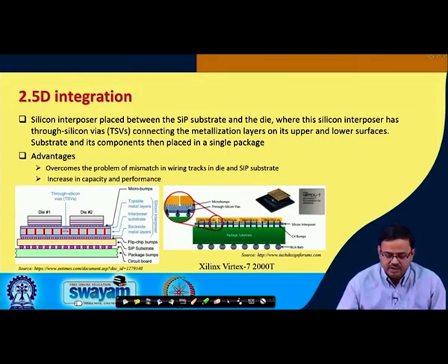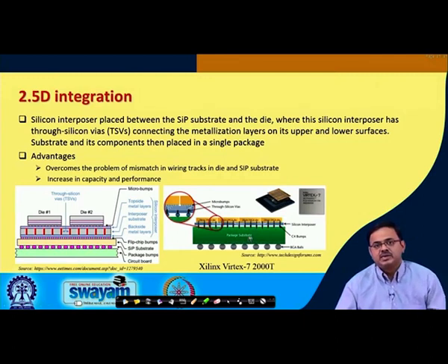So, you see here you have 4 of these FPGA flip chip dies. Okay, it is flipped, the pin grids are at the top, and then you have a silicon interposer, and then you have these C4 bumps which we saw in flip chip, controlled collapse chip connect, if you recall, C4. And then you have the package substrate, and then the BGA balls.